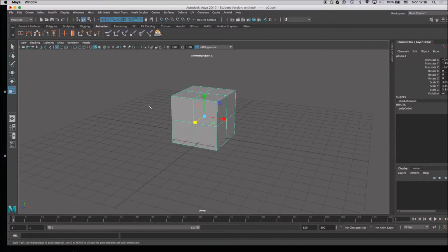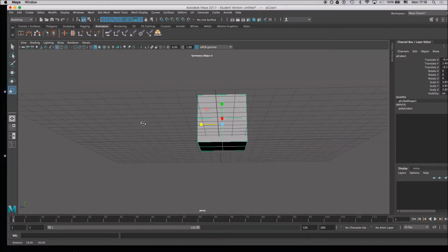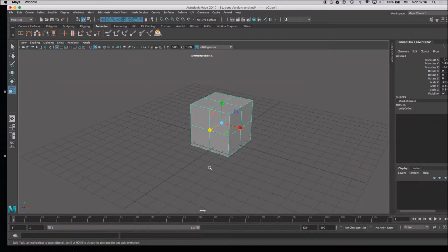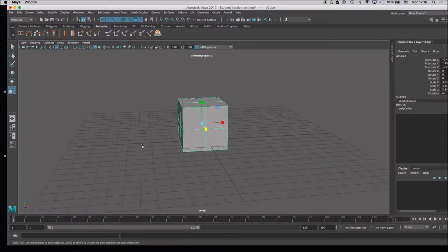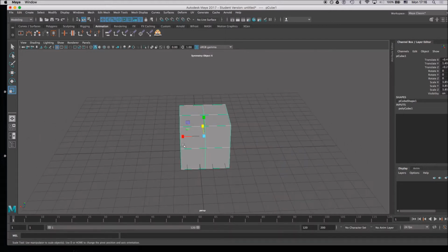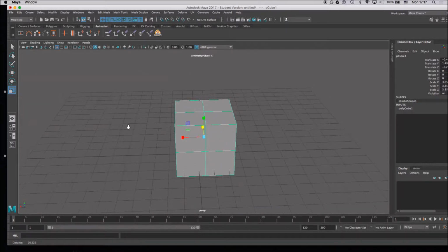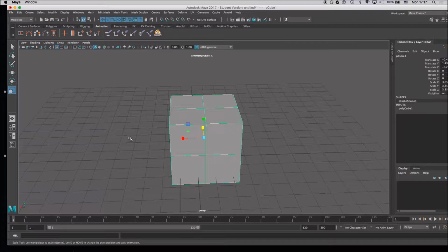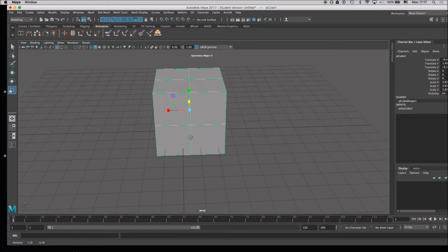And right. So you guys might not be able to move your cameras. So how we do that is all of the camera operations to navigate Maya are done with the Alt key. So you hold down Alt, and then if you left click, you can rotate. If you hold down Alt and you right click, you can zoom in, zoom out. And then if you hold down Alt and you middle click, that lets us pan the view.